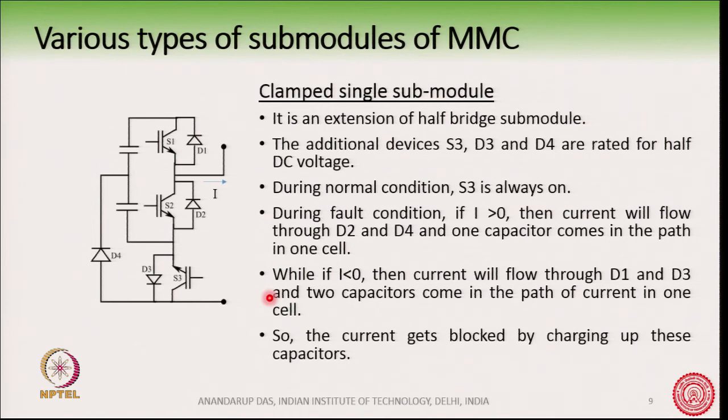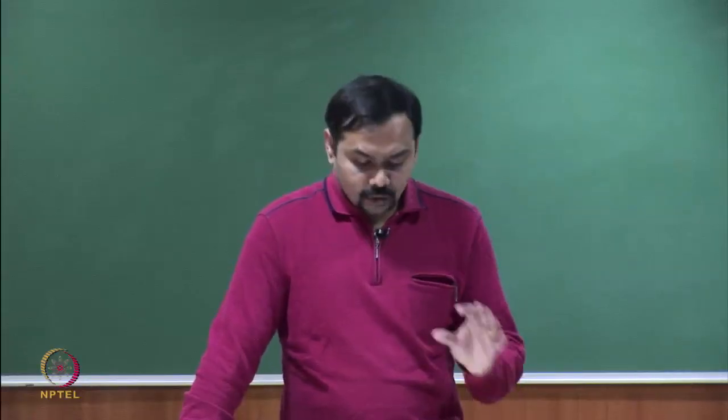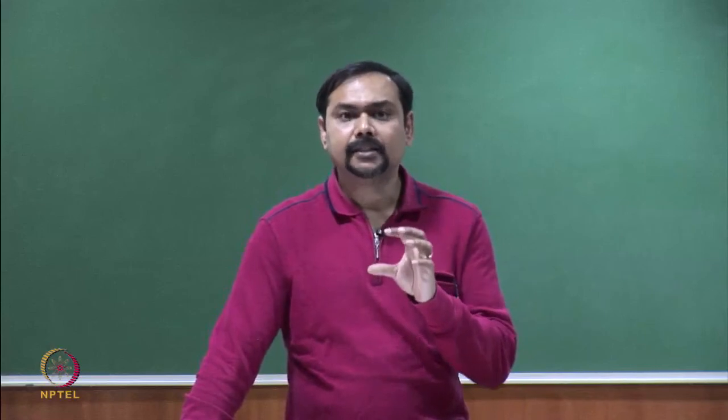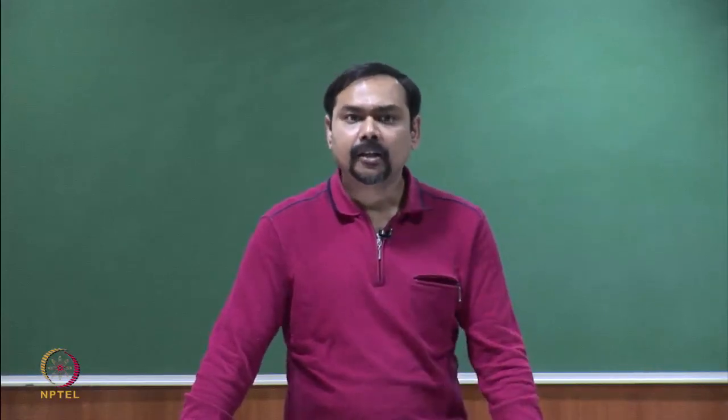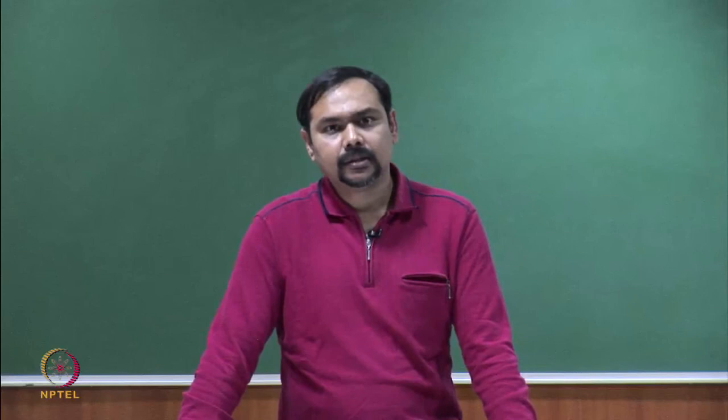So, we see that in this topology during the fault condition there are always these capacitors which are coming in the path of the fault current.